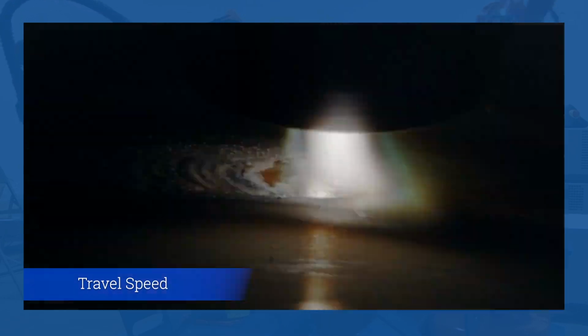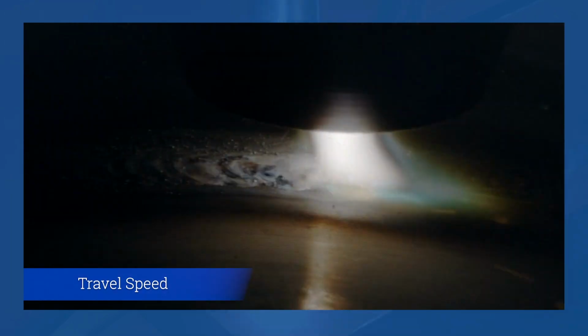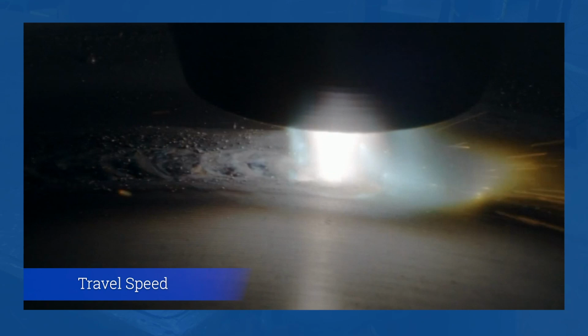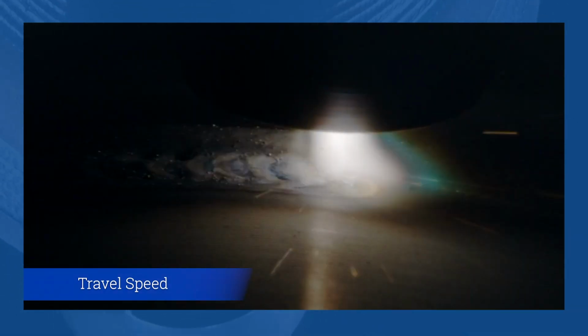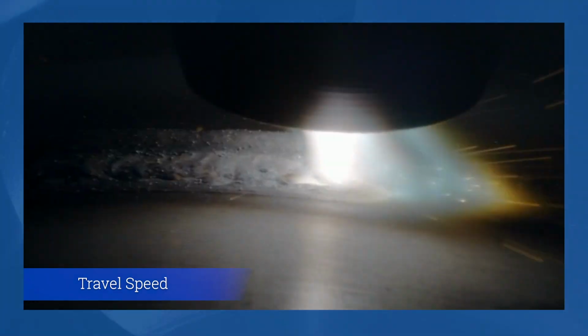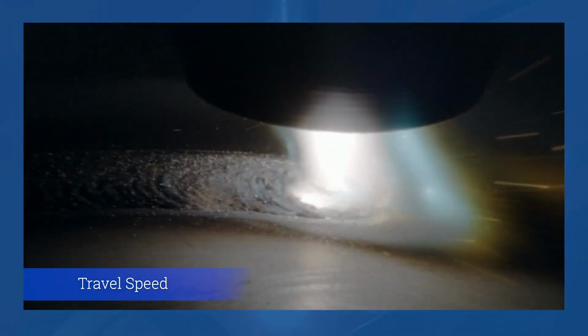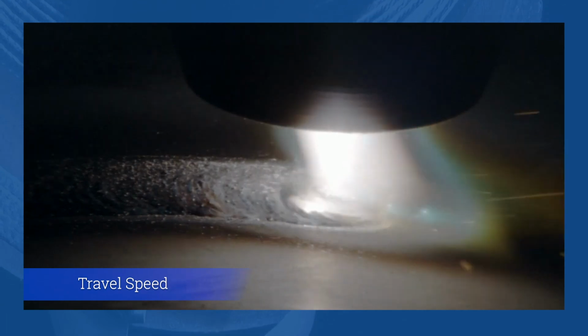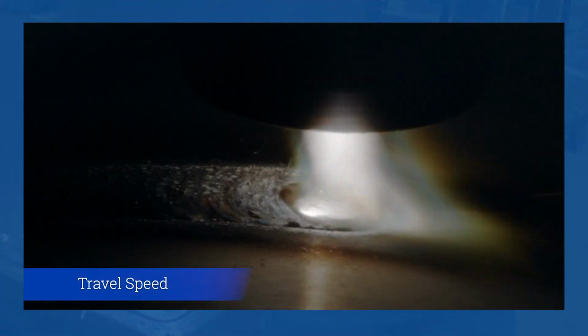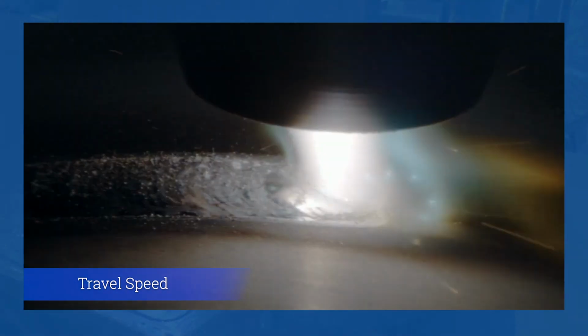Let's talk about travel speed, another key variable that you will be having to adjust in production. Everything's set properly now, but once we speed it up, you see that the pulse rate is not keeping up, and neither is the weld. The weld's not following. So if you don't see that stack of dime ripples behind your arc, then you're probably traveling too fast. So now we're going to slow down too slow. Now what's happening here? Well, this could be an acceptable weld if you're looking for a thick weld buildup, but you may be getting excess dilution, and in taking this to extremes, you'll actually get lack of fusion because the weld rolls ahead of your arc.